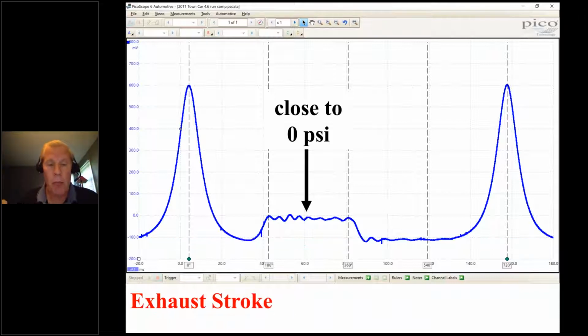So let's move to the exhaust stroke. Once upon a time, the exhaust stroke in this analysis was considered to be the easiest stroke to understand. Now, we have opened the exhaust valve 60 to 30 degrees before bottom dead center. So the valve is opening, and by the time the piston has moved upward to clear out the byproducts, and in this case it's just removing air, the valve is open and there should be no obstruction. There should be no, what I call, exhaust path restriction.